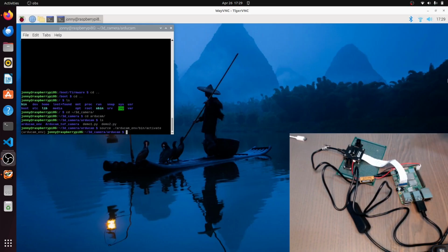I've mounted the stereo camera on the perf board, and then I put the Arducam Time of Flight camera on top of that. So I've got this exactly in the middle of the two lenses, and I've counted the holes and everything to do that. And then I've got everything connected to this Raspberry Pi here, and I'm running Bookworm on the Raspberry Pi. You can also run Bullseye. I wouldn't recommend running anything older than Bullseye, because you might get some issues with OpenCV installation and that kind of stuff. I think OpenCV will install a little bit easier on Bullseye and Bookworm, in my experience, and other stuff.